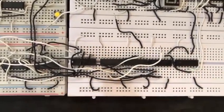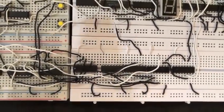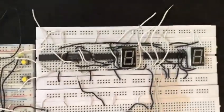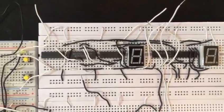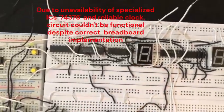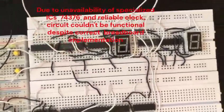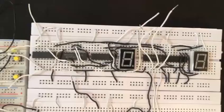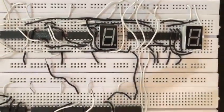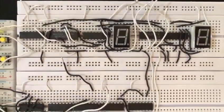After the calculations are done, and the floor is incremented by however much we want it to, it is then sent to the display logic. This 7-segment display is used just as a 10-second timer to add a delay between the moving of the floors, and this is used to display the last or the final destination of the elevator.